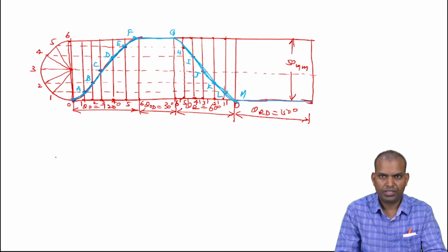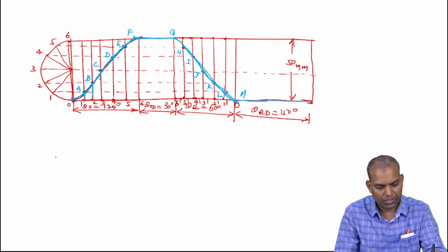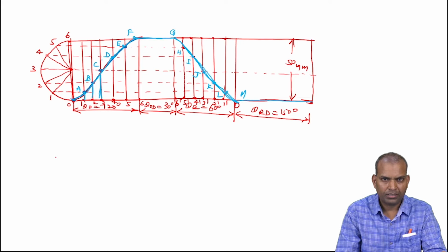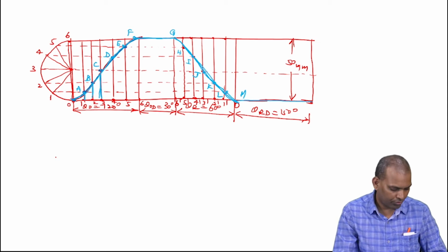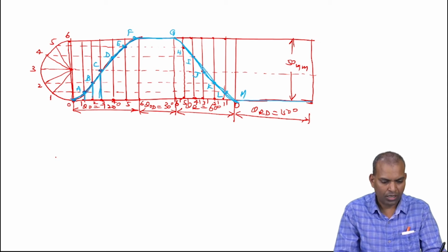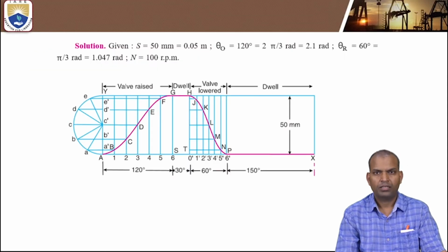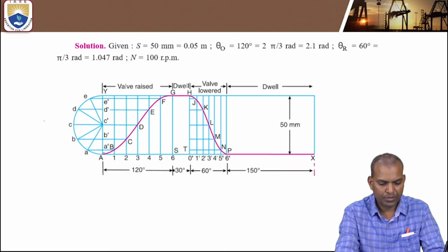Like that, in different notations, because these are the vertical displacements required for us to draw the cam profile. While drawing the cam profile, we need these vertical displacements. Okay, now let us see how it looks. Really, this is the diagram. So the curve looks like that. This red color represents the SHM curve of the displacement. The same procedure you have to follow.